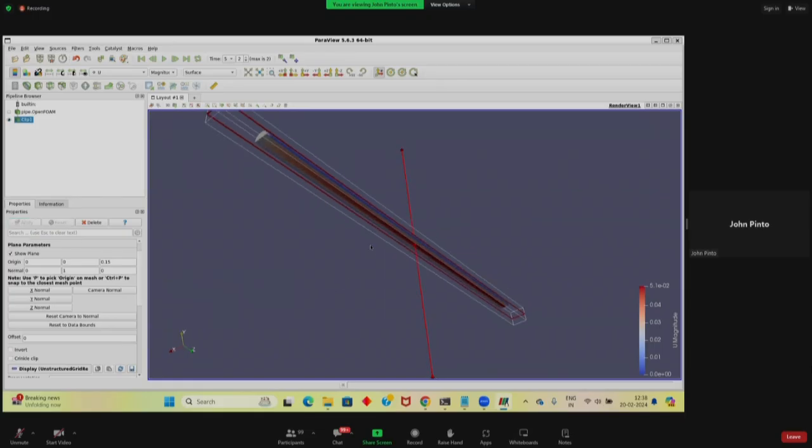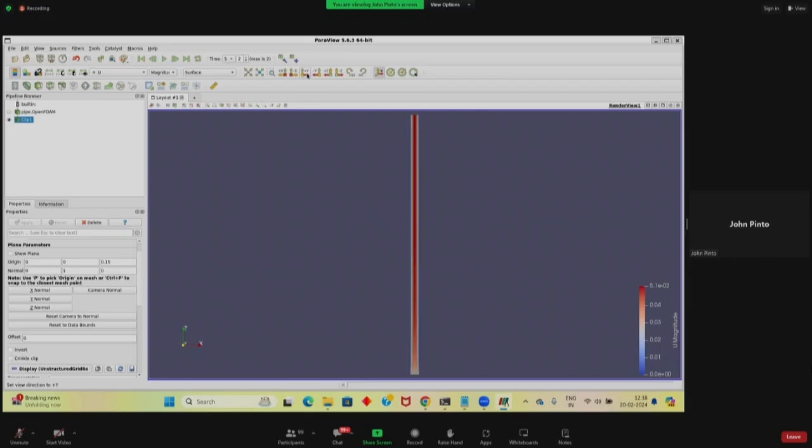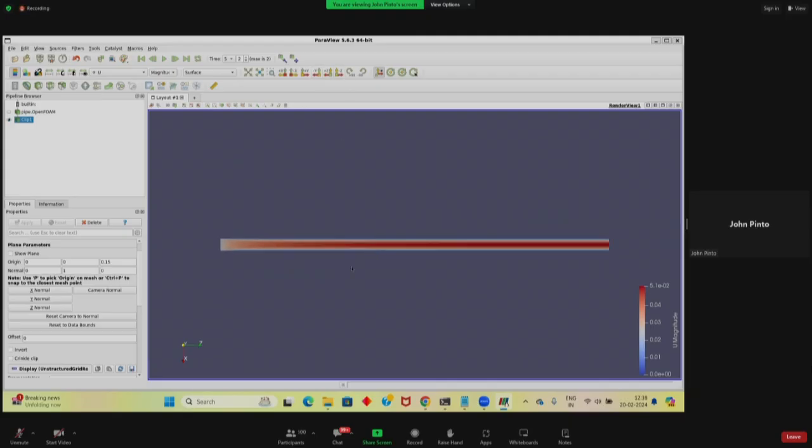So it shows the velocity profile. Now, if I uncheck this show plane, then all of this, whatever had come, will go. Now let's see how it looks. Yes, and rotate it by 90 degrees. This is what I'm doing by this plus X, Y, Z, so I get a better view. If you see the flow, it is coming with certain velocity and the flow is developing as it is going inside. You see the center line velocity is increasing and the flow is getting developed. So this is one way of visualizing.